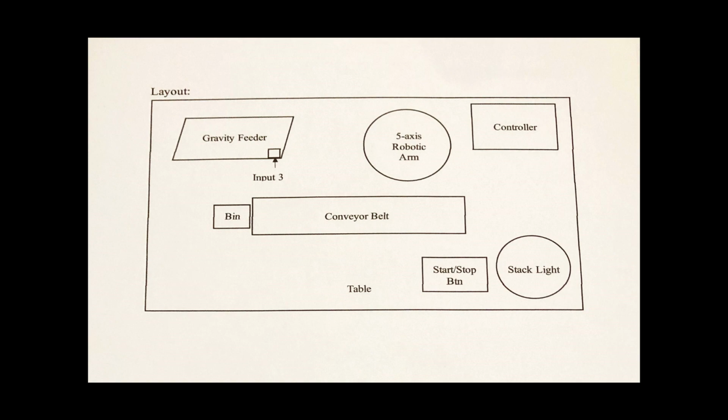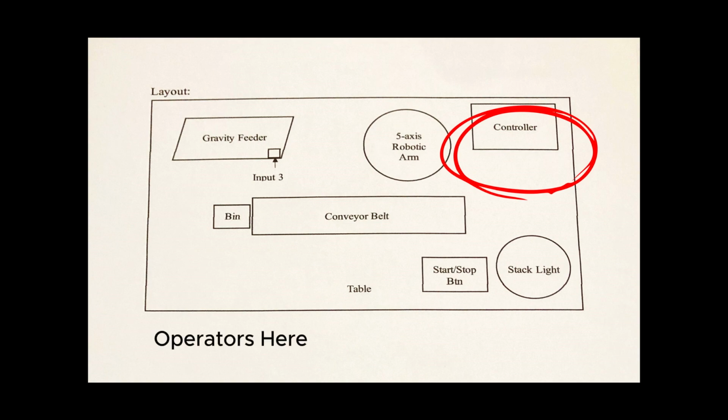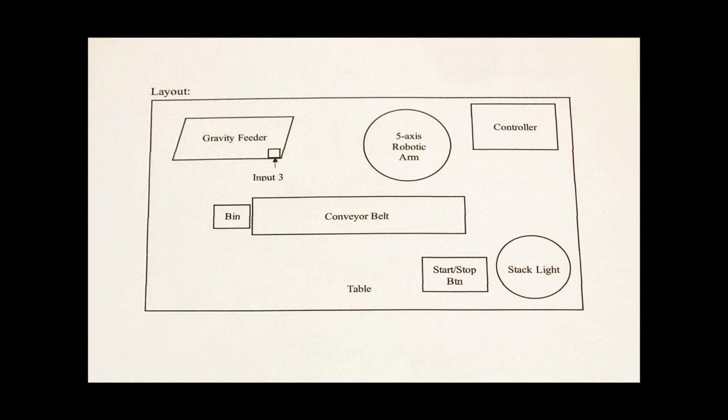When recording safety, we implemented different procedures to ensure our safety. Because we had soldered wires and breadboards, we moved all the electrical components into the corner farthest from us so we don't accidentally shock ourselves. We used 2 tables as a base so that we can distance ourselves from the parts as well as the parts from each other so they don't accidentally knock each other. We secured all the parts down onto the table so they don't accidentally move, tape for lighter items, and bolts for heavier items. Following OSHA safety guidelines, whenever we were using the robot, we'd always roll up our sleeves, tie our hair back, and put on safety glasses. When working with electricity, we'd always make sure to turn off the controller and any additional energy sources.